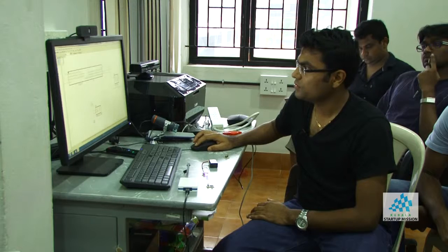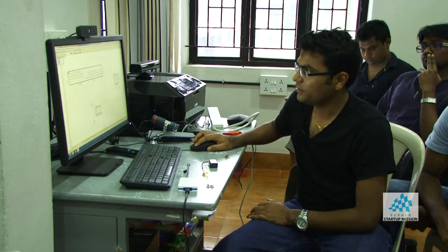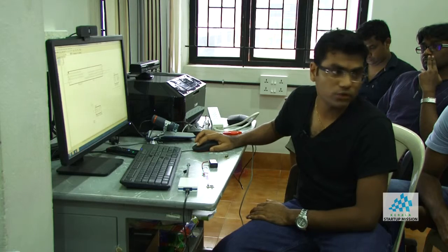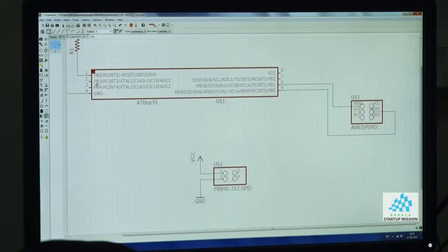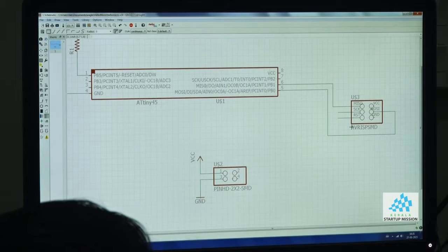Okay, so now reset here is all the way here. So what I can do, one technique, is I can label my pin. First create a half net. Just do this, double click. You are not ending it, it's an open-ended wire right now. And then you're going to just label it. So I'll do label.